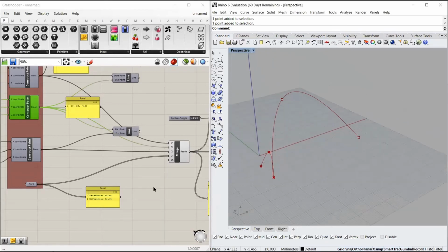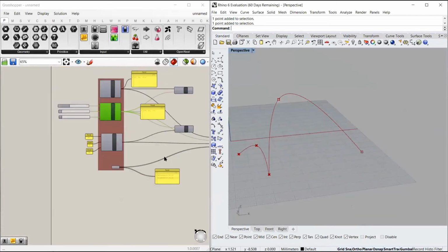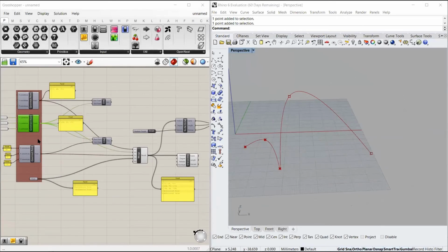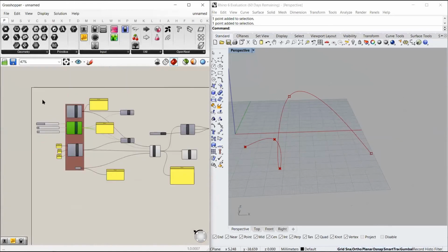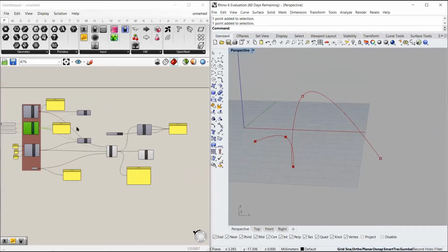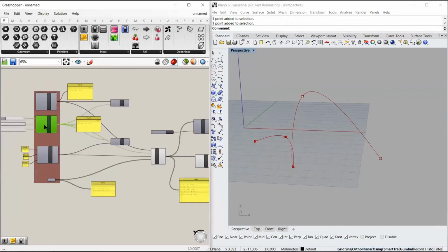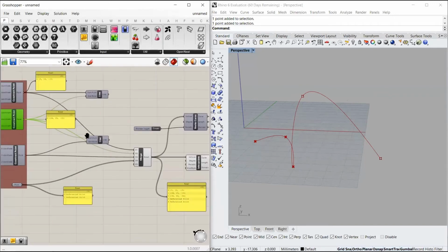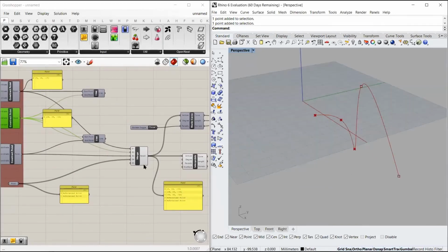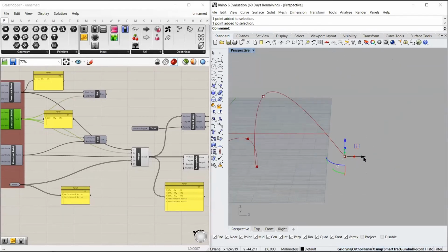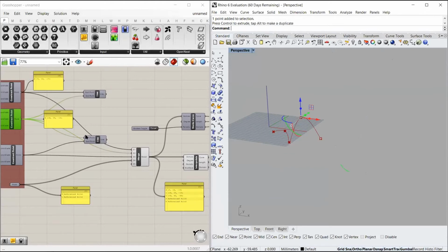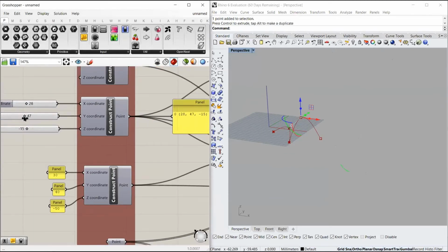And I will create something like this. Now you can parametrically control this curve using these parameters. Like if I change this, you see the curve is also getting changed. So we are trying to generate something that is called a digital framework, or basically a parametric model in which we can control this final geometry with many different parameters. For now, this geometry has parameters like this, which has been directly referenced from Rhino, or parameters like the XYZ coordinates of these curves.